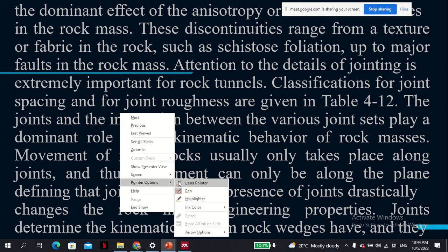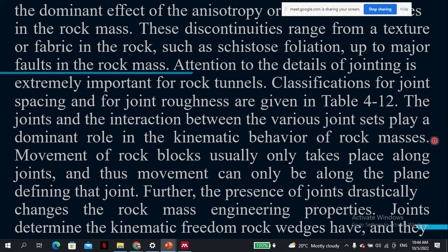What is this thing we call rock mass? It is not an isolated block of rock, because an isolated block of rock might be uniform, might have good strength, but how does this rock behave in conjunction with the entire rock mass, the different blocks forming it? These rocks are only as strong as the weakest joints. So in rock classification, a lot of attention is paid to the joint, the nature of the joint, the distances, the spaces.